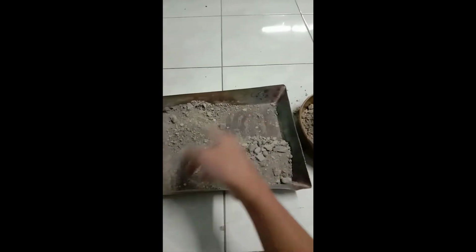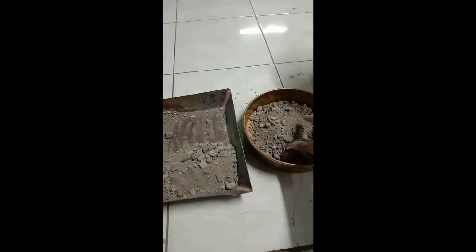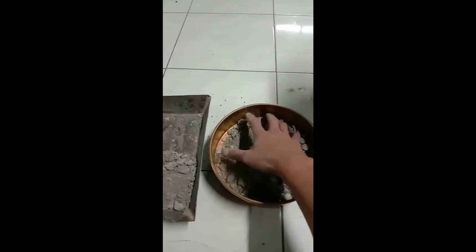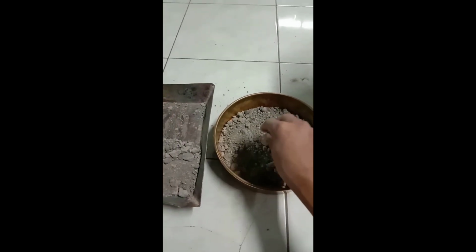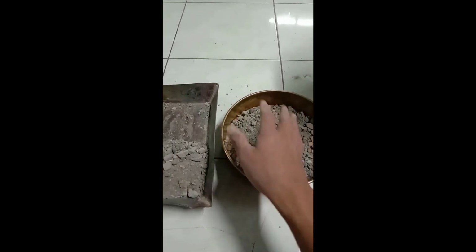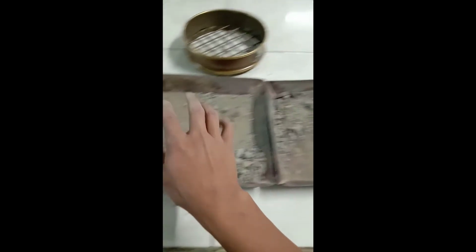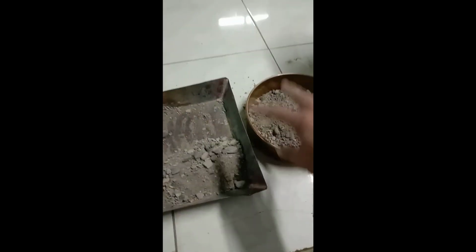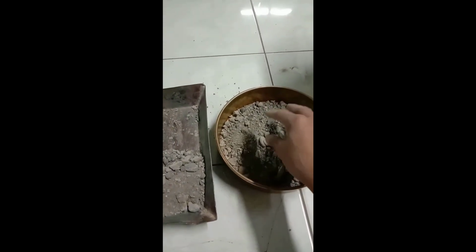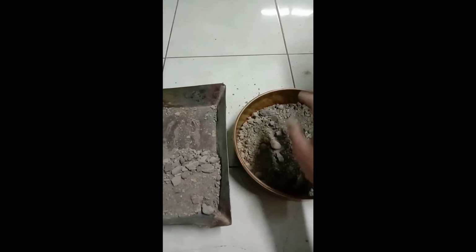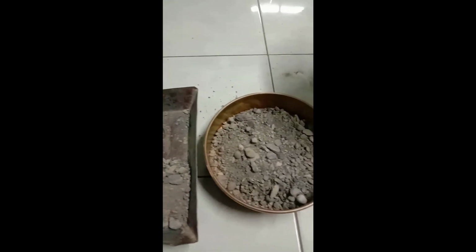We remove the opposite parts, and then we consider that as our sample, which we are going to test for mechanical properties. So again, the objective of this procedure is for you to reduce from a bigger amount of sample to a smaller amount of sample. Let's say that is what you only need for the analysis of the chemical property of this aggregate. So that is our experiment.